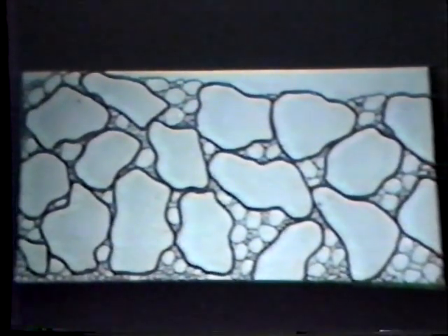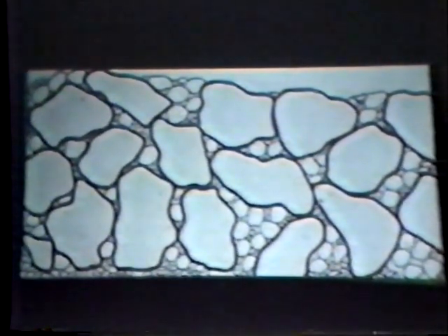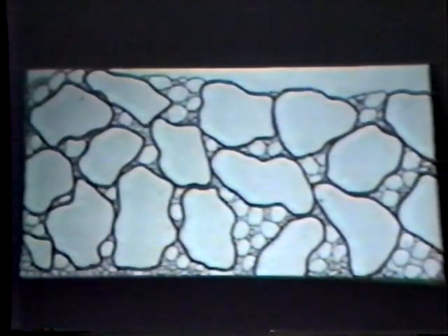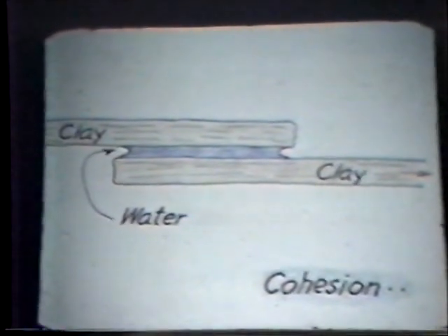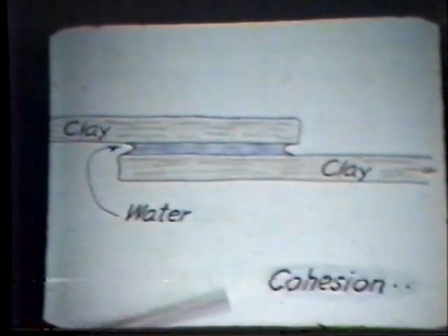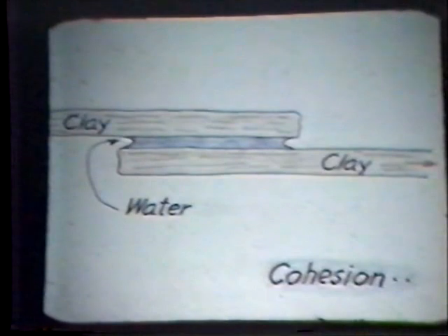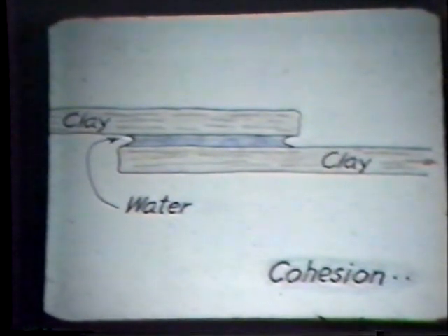Now, the interlock between particles is one of the principal sources of strength, and generally speaking, for base course materials, you want to be sure you have enough little guys in between the big guys so that the big guys can't roll around, so that they can get good strength. One problem is clay. When you have clay, it's a platy particle, and if you've ever tried to walk around with a big stack of books, those are platy particles too. You have to push real hard together to get any strength, to be able to support a column of books on its side, for example.